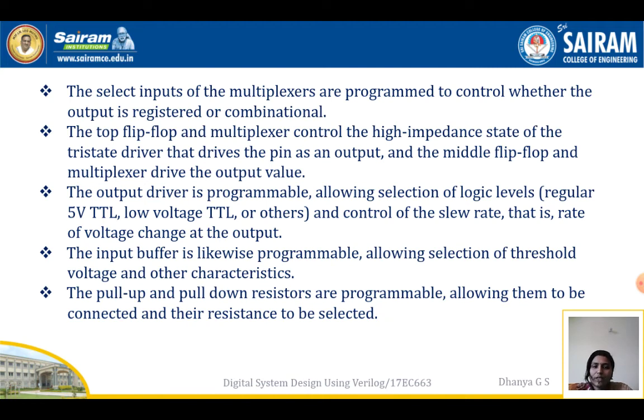The output driver is programmable, allowing selection of logic levels and control of slew rate, that is the rate of voltage change at the output. The input buffer is likewise programmable, allowing selection of threshold voltage and other characteristics. The pull-up and pull-down resistors are programmable, allowing them to be connected and their resistance to be selected.